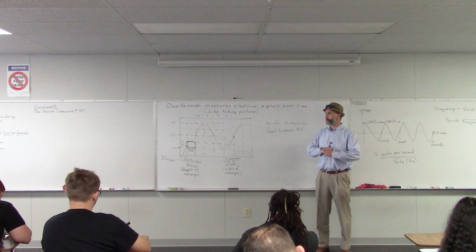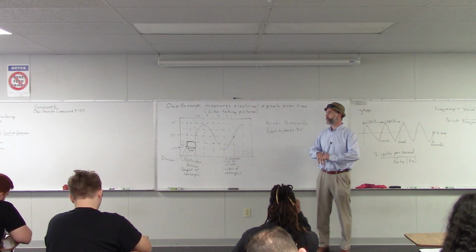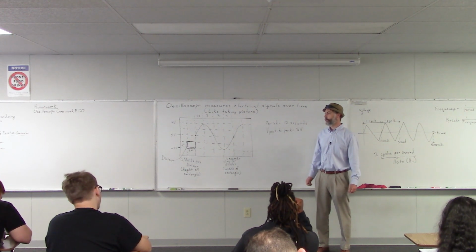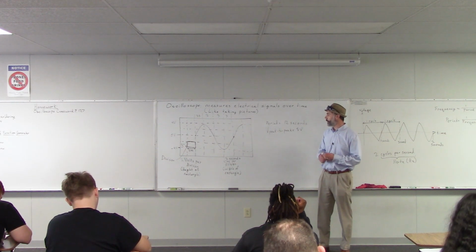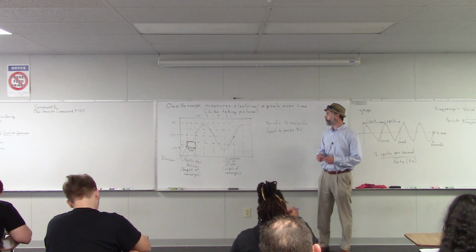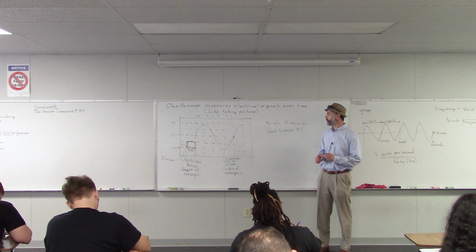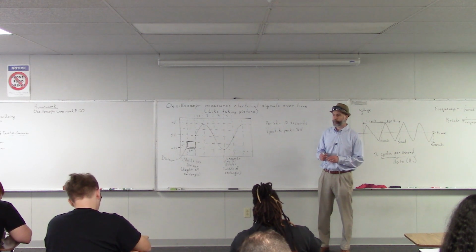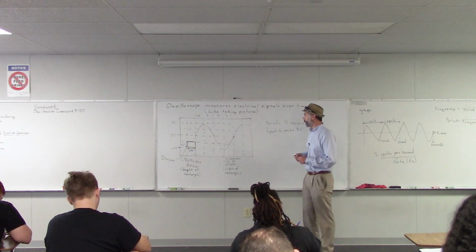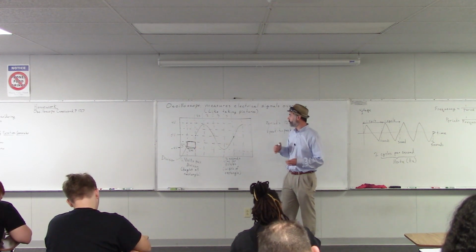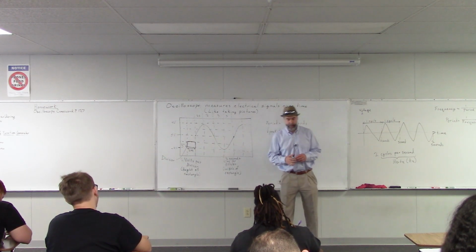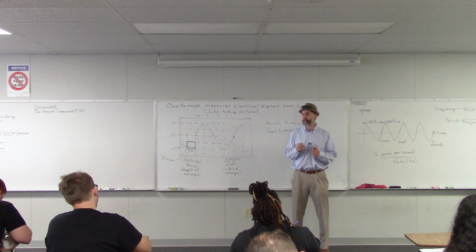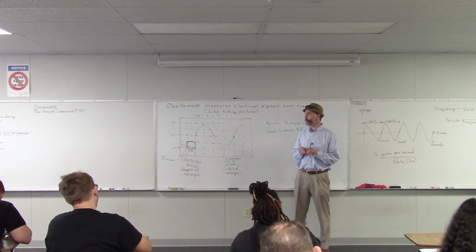Will the measurements always hit the bottom of the next rectangle and like a full rectangle? No, not necessarily. Sometimes you just have to estimate. This is a good way of getting close, and then the oscilloscope actually has some built-in measurement functions that will give you an even more precise measurement.